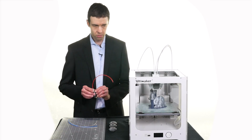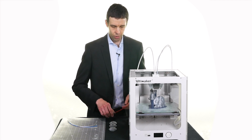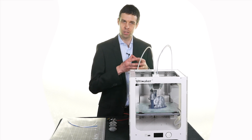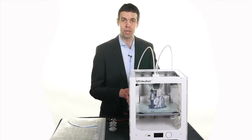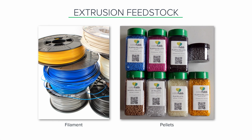Now in this printer, the heating mechanisms sit on the moving platform, going in X and Y, but the forcing mechanisms, what drives the filament forward and counteracts the viscosity at temperature, are attached to the frame. That's what's called a Bowden-style mechanism. Some industrial AM systems use filament as the feedstock, like smaller ones, and others use pellets increasingly as the feedstock, which is a lower cost way to provide a large volume of material and enable higher throughput printing.